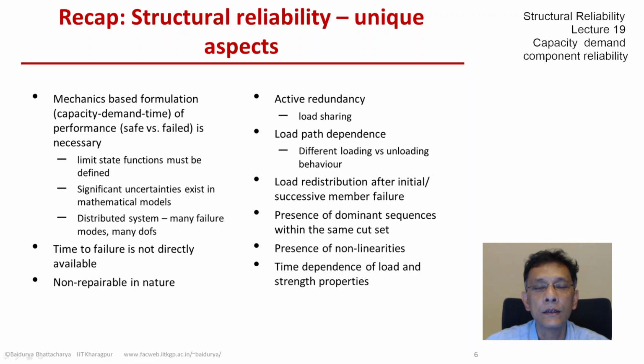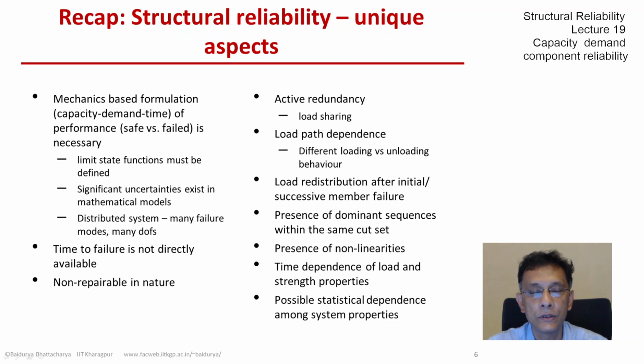And obviously the spatially distributed system properties, whether it be elasticity or yield strength or other properties, there could be dependence in those properties distributed around the system. So all of these things make structural reliability interesting and challenging to analyze.